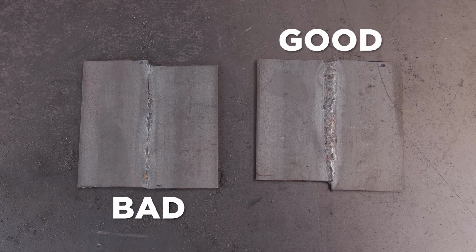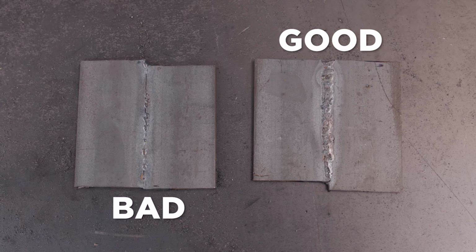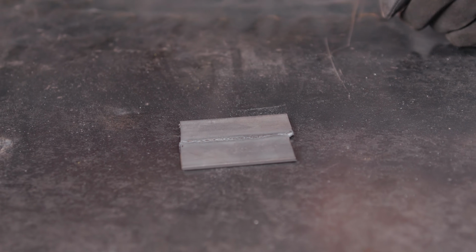The lack of penetration means that your weld bead hasn't gone all the way through the joint. The groove or root of the metal hasn't been completely fused. This is a lot easier to see on a butt weld, as you can flip it over and check the back side to make sure the weld bead has fused on both sides and filled in the entire space. Like a lack of fusion, if you've got shallow penetration, the weld can be deemed faulty for crucial situations.